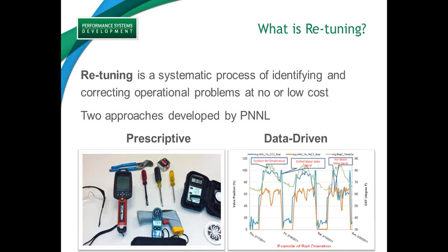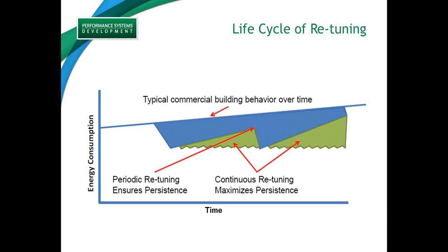So, is this retuning process a one-time thing you apply, like you apply for LEED or you do an audit? And the answer is really no. It's best utilized as part of the maintenance program, and it's just building it into your maintenance practice. Typically, the first time you do retuning on a building, it's the most time intensive because you're understanding your building automation system, getting the data out of it, setting up the trends, doing the initial analysis, just understanding your building.